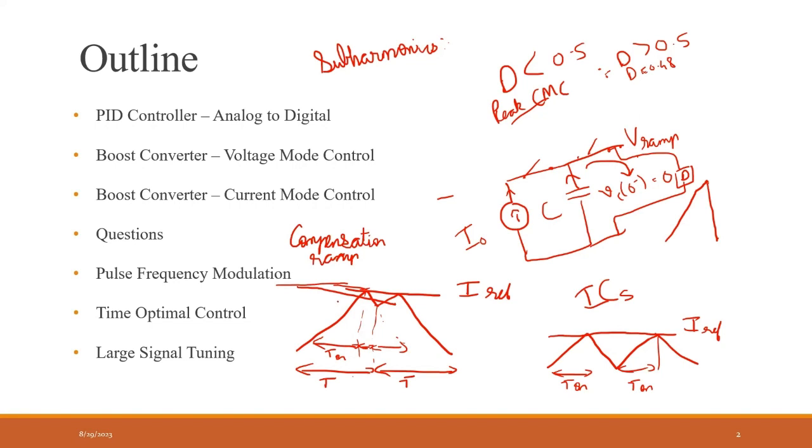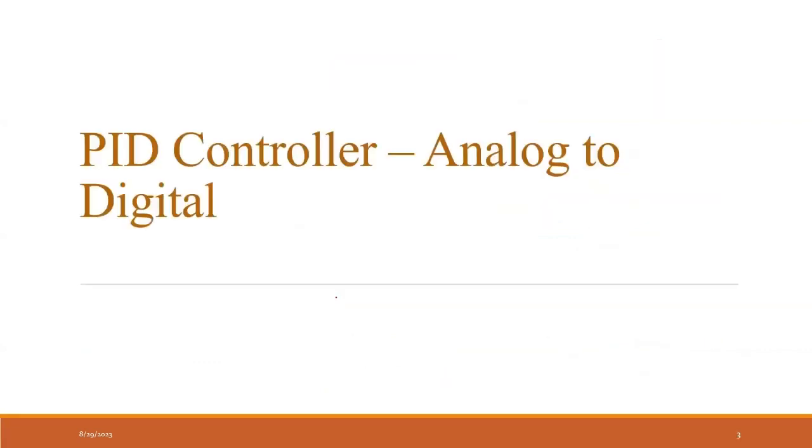If you are doing peak current control, first we need to switch off the top switch, then we need to switch on the bottom switch. So that is the reason why we are sensing on the top switch for the peak current control. Can I understand it that way, sir?